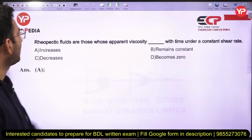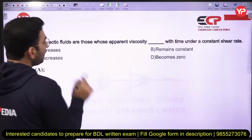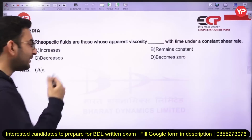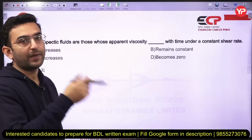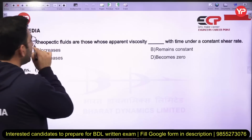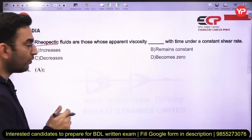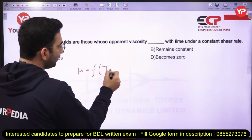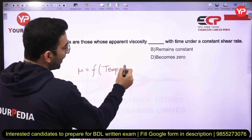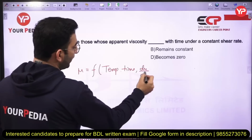Next part, rheopectic fluids are those whose apparent viscosity increases with time under a constant shear rate. Now just see one more thing. When we talk about non-Newtonian fluids, the fluids are classified on the basis of time independent and time dependent. Specifically, rheopectic fluids are considered time dependent fluids. So in this case the viscosity is depending upon time, along with that it is depending upon du by dy.